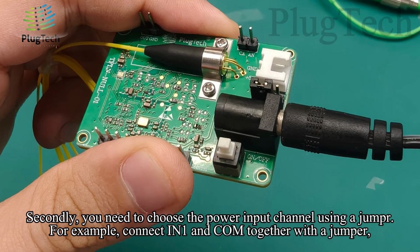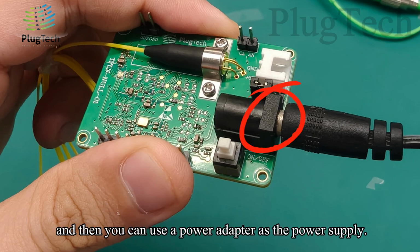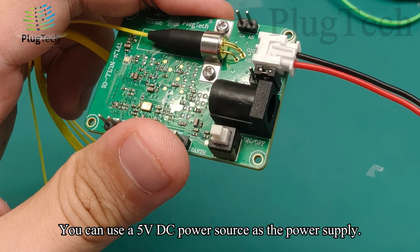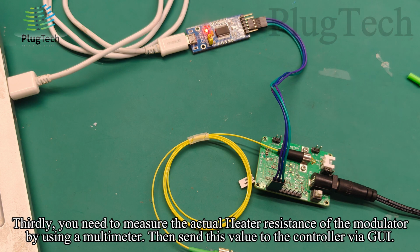Secondly, you need to choose the power input channel using a jumper. For example, connect IN1 and COM together with a jumper, and then you can use a power adapter as the power supply. If you connect IN2 and COM together with a jumper, you can use a 5 volts DC power source as the power supply. Thirdly, you need to measure the actual heater resistance of the modulator by using a multimeter. Then send this value to the controller via GUI.